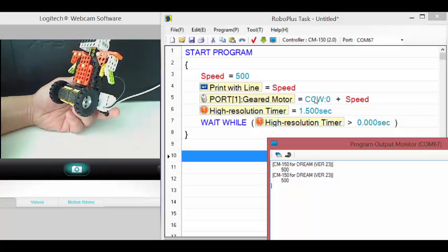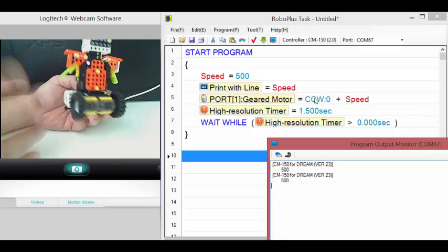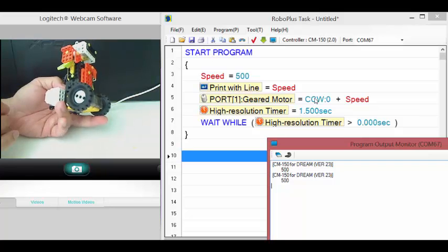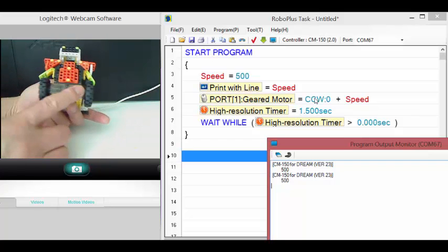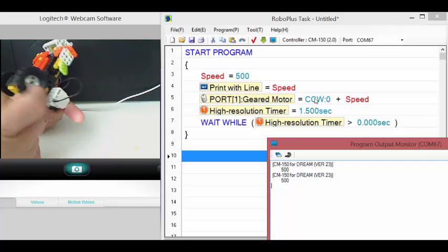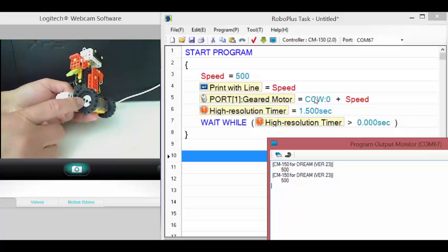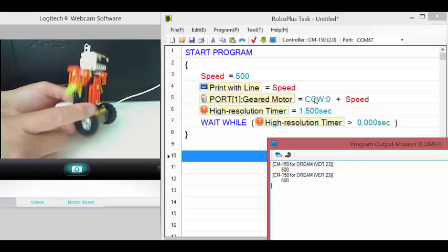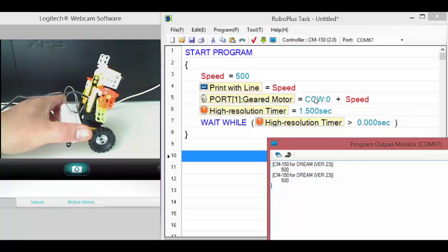Your program may be different from the instructor's program and from the other kids in the class, but it's fine as long as you know that's how your robot works. There's nothing right or wrong, because you assemble it a certain way and control it a certain way. So we figured out this one is port 1 and counterclockwise is good. That means this one is going to be port 2, and it has to go clockwise in order to go forward.